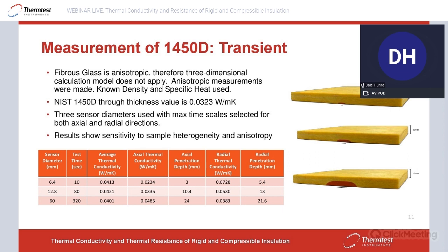So in this case, it's a unique use of that one time in that one sensor that averages that particular amount of material in each direction for that number. But if you underpenetrate it, or rather penetrate less than that or penetrate more than that, your actual value changes. And that's because it is not repeating. So it's really important that when you use an anisotropic approach with a transient type sensor, that your material is highly organized and repeating to get valid results. Otherwise, what are you measuring? You will have error associated with that.